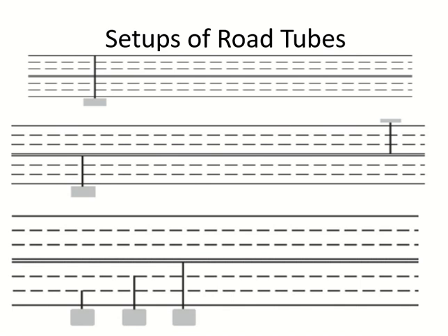The pneumatic road tubes can be put in different setups depending upon what type of count you are looking for. If I'm looking for the total count of the road, I don't care about which direction or which lane, so I can lay out one tube from one end to the other, and one counter only. The first setup will give you the total of the entire road, but you will not know how many in each direction and how many in each lane.